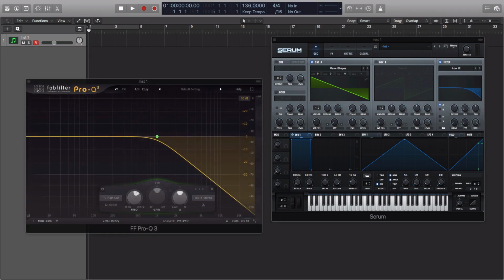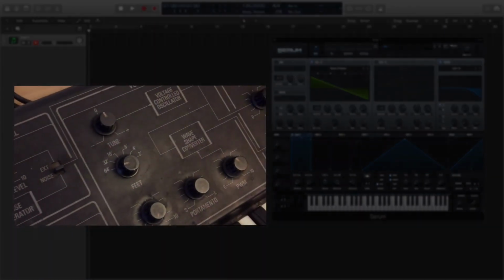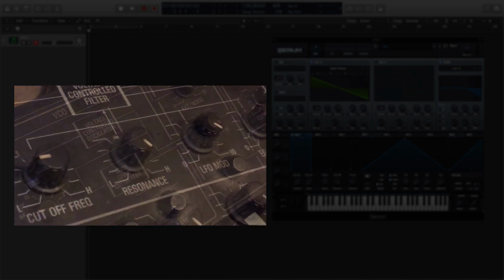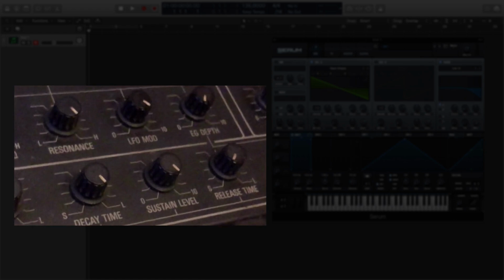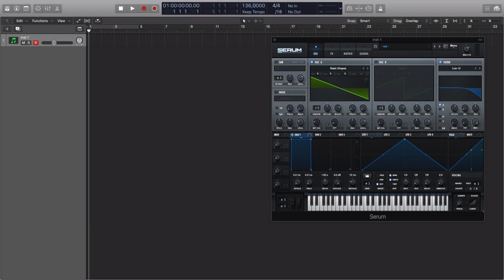Filters act much as an EQ, but the big difference is that the filter sometimes helps print the signature of a sound, particularly when we talk about old analog synths, where a specific component is inducing a specific characteristic on the electrical signal, making it different from the others, therefore printing a different and unique color. That's why the same waveform with the same filter type and slope can sound different on two different synthesizers, because the oscillator and filter components have their own signature.